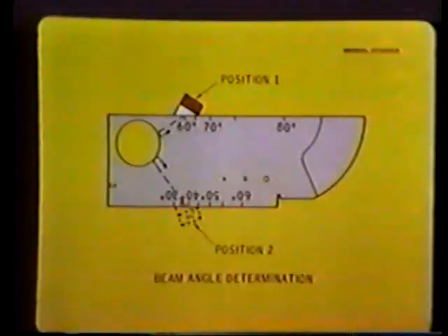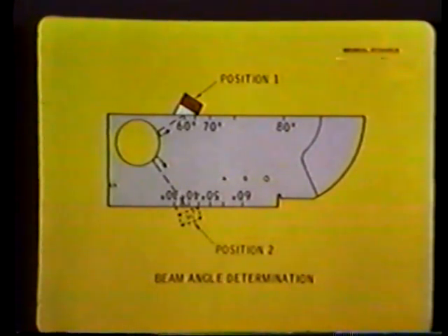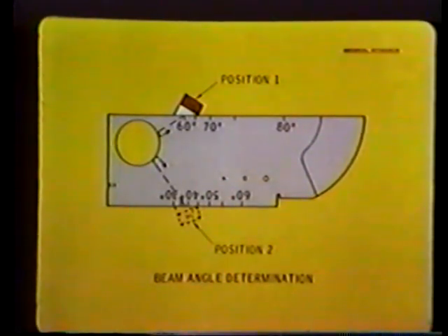To check or verify an angle beam transducer's incident beam angle, the transducer is coupled to either of the narrow parallel sides of the block and moved back and forth till a peak signal is obtained from the 2-inch diameter hole. The angle of refraction is then read from the appropriate scale on the side of the block.